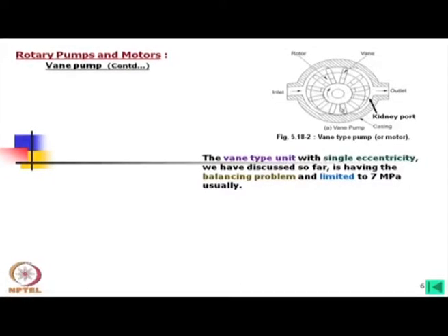However, all these vanes are reciprocating. So, there will be dynamics, there will be vibration and a balancing problem. As such, for a single pump, this cannot be eliminated.